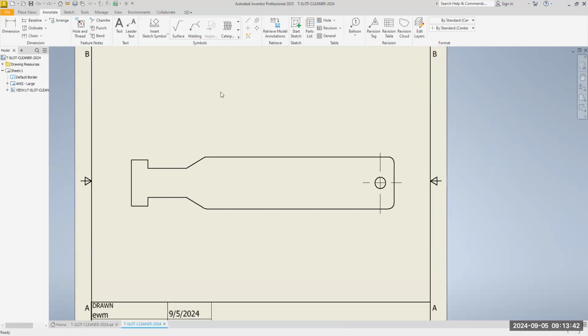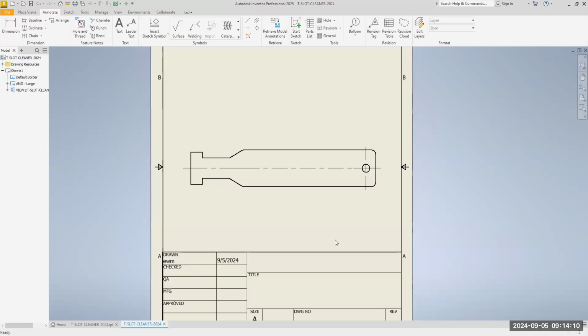I'm going to show you another way to put in the center mark. Do the bisector right here. This is called the bisector center line. Click here, click this edge, and click this edge. Do a right click, cancel. Now again, I'm going to hover above that grip, hold down my left mouse button, and drag it over this way. All right, I hope you have this.